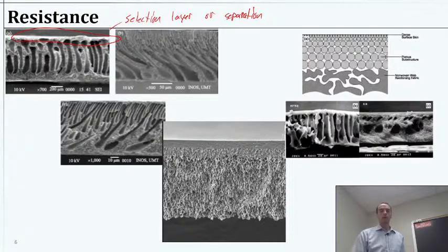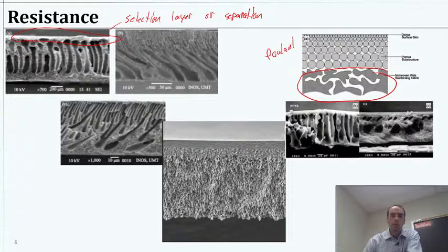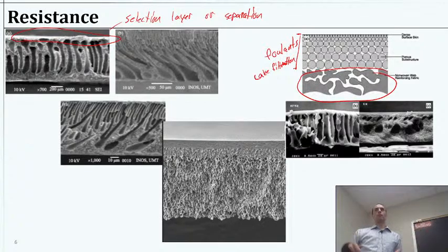Of course, if we have fouling, let's imagine over here, this is our membrane, and these are particles being stuck and loaded and fouled on top of the membrane, then we end up with a scenario we'll talk about where, if this is all foulants, we might be filtering through the foulants, and we would end up calling that cake layer filtration, where we are filtering through all that stuff that has been added onto the surface. That will improve our performance in terms of what we can reject and how much of it we are rejecting. We'll reject smaller stuff because of the fouling, but that's going to decrease our performance in terms of the flux, the pressure requirements, all of that. Okay, so a cake layer filtration is what I meant to say.